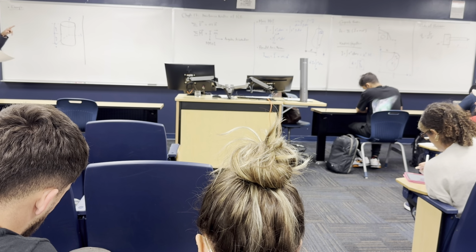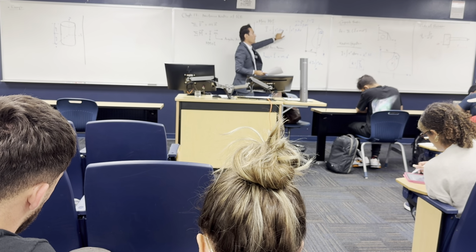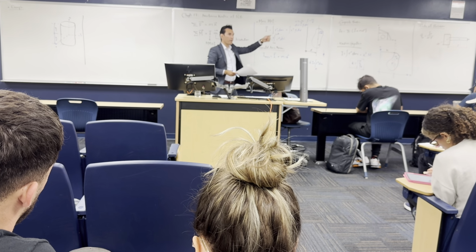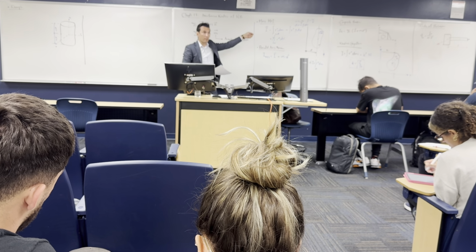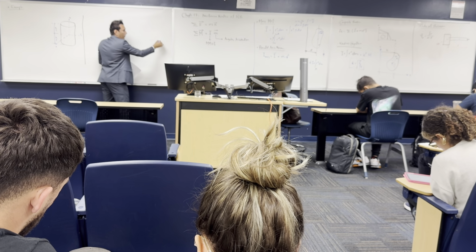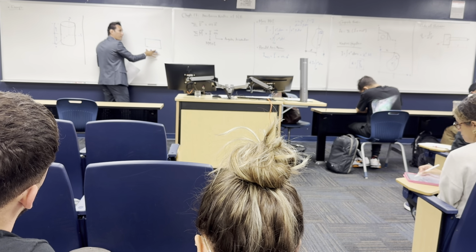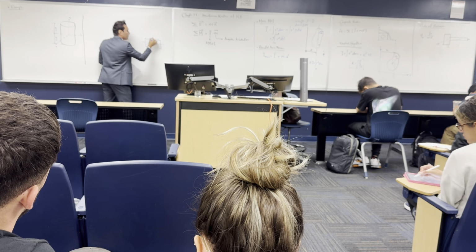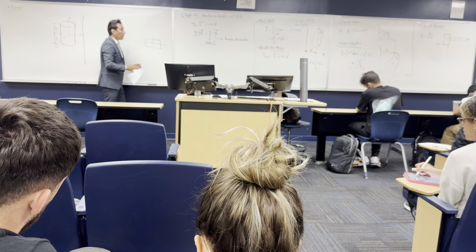Oh, we talked about the mass moment of inertia, and the mass moment of inertia is r squared multiplied by dm. Do you guys remember the first moment of area and the second moment of area? There's the first moment of mass and the second moment of mass. Okay, so I just want to make sure that we have these basics before we start. If we have this mass, and this is the centroid here, and we are getting the mass moment of inertia of each one of these about the x-axis.